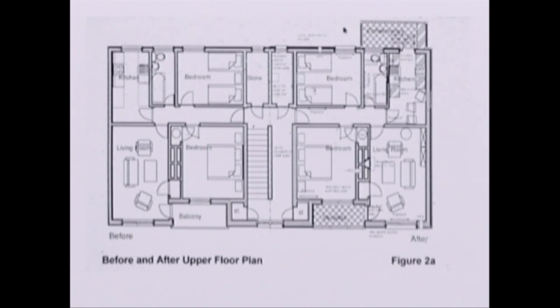That then leaves the minor bedroom and the bathroom. The bathroom would probably have a towel rail and still a small radiator possibly in the smaller bedroom. The kitchen wouldn't need any heating at all because it's got plenty of incidental gains from the equipment.